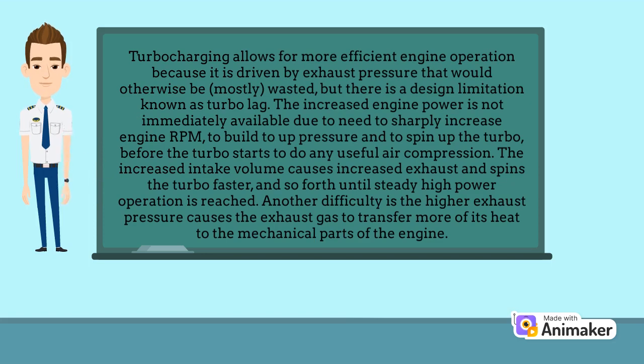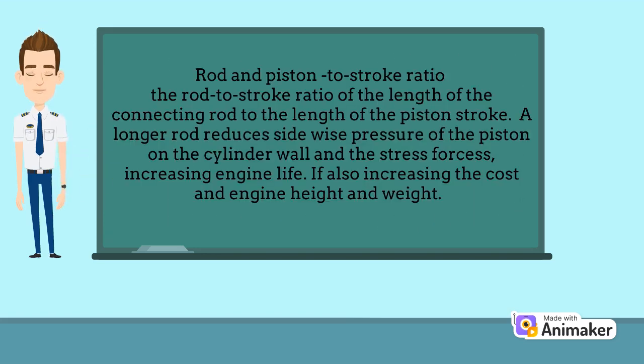Increased exhaust pressure spins the turbo faster, and so forth until steady high power operation is reached. Another difficulty is that the higher exhaust pressure causes the exhaust gas to transfer more of its heat to the mechanical parts of the engine. Rod and piston to stroke ratio.